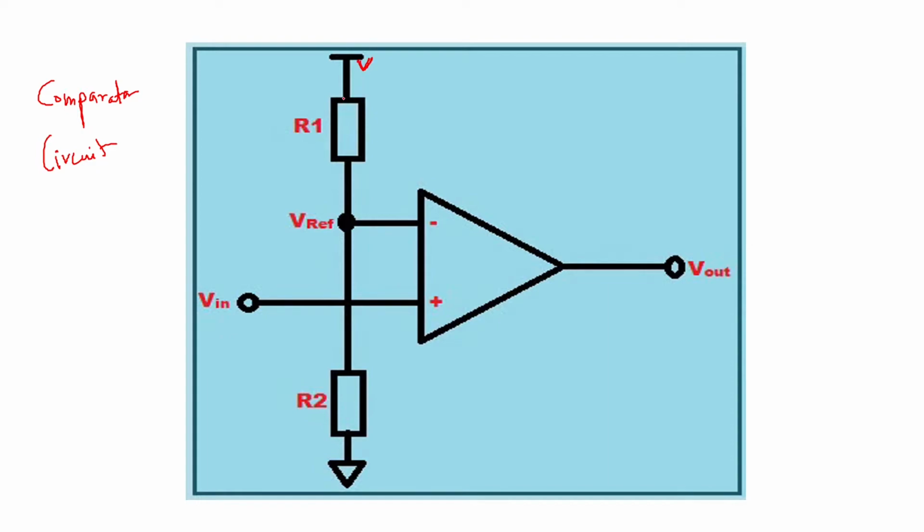That voltage goes through a resistance R1, and is taken as a reference voltage at the inverting terminal, minus. Similarly, you give one input at the non-inverting terminal, so here you can apply a certain input with respect to ground.